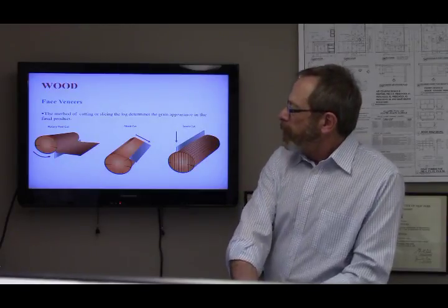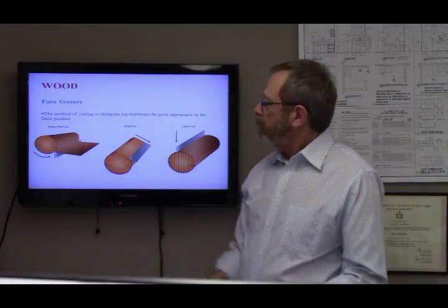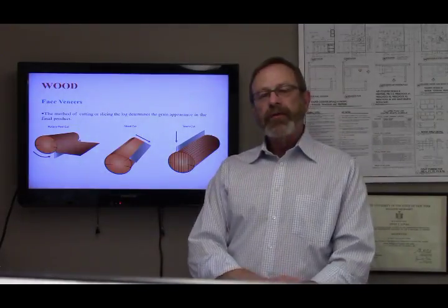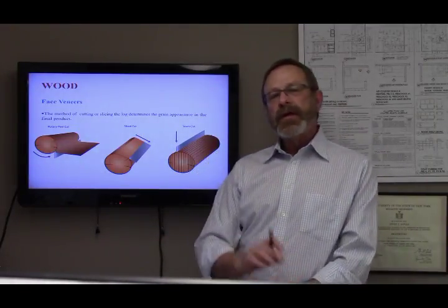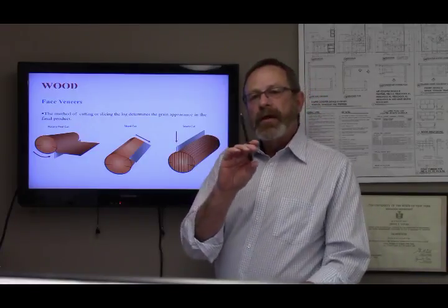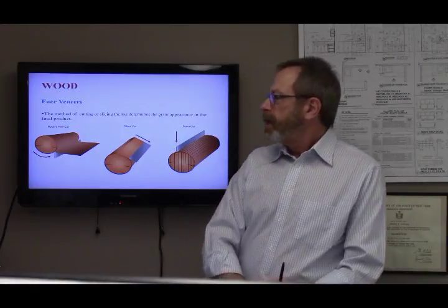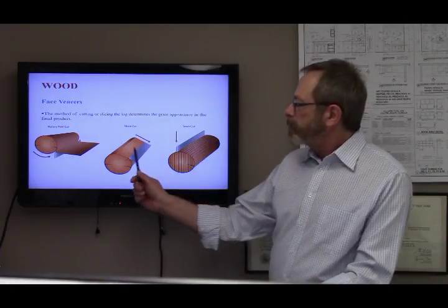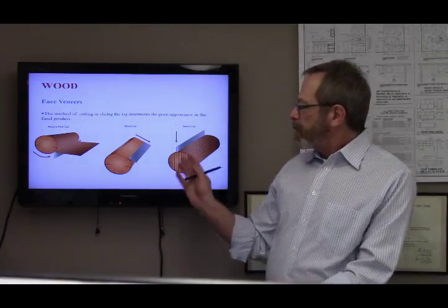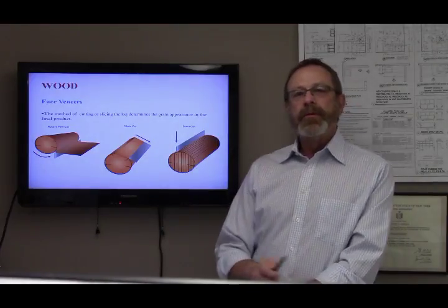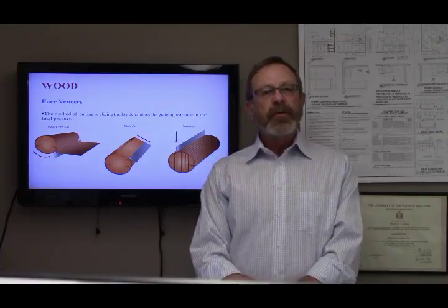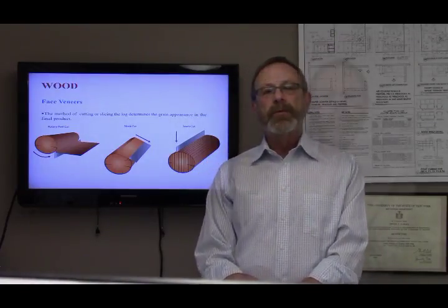To create a veneer, we have either rotary peel cut, slice cut, or sawn cut. The rotary cut is the cut that is used to create the inner layers of those engineered plywood boards. The outer layers can be decorative and be composed of any type of slice or combination that you would want. As we're going to see, the type of slice determines the appearance of that outer layer wood.